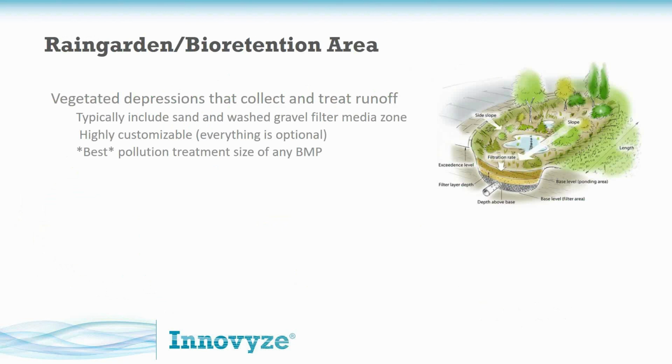And something in the first webinar this morning, someone asked, my general, when I was a consultant, if I had literally 30 seconds to figure out the even starting size for these facilities, I tend to go with between 2 and 4% of the impervious area washing into this facility. That's, depending on where you are, generally a starting point. So if you could say, all right, 2 or maybe 4% of that square footage, you're going to need a facility about that size.